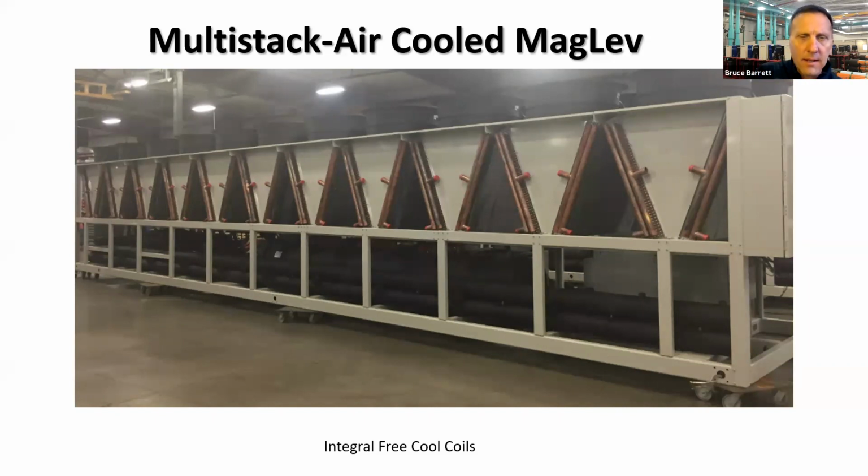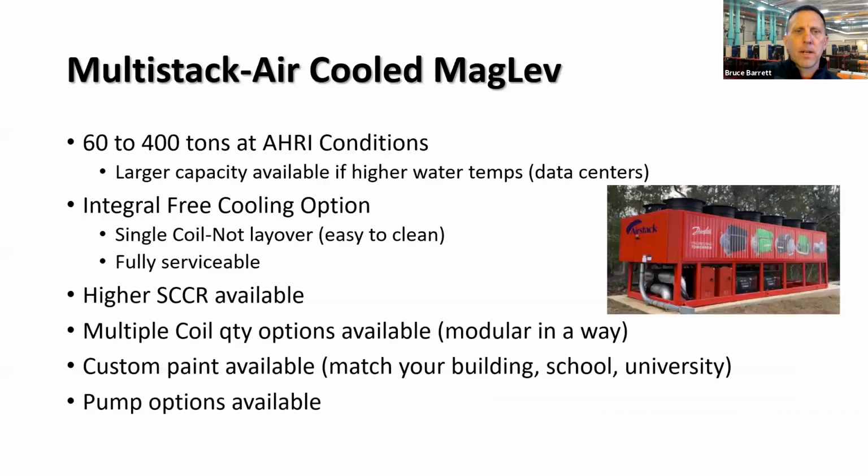This is an 11V. So it's close to 300-ish tons. We do go from 60 to 400 ton air cooleds. Again, larger capacity data centers, we might be able to go up to 550 ton, oftentimes because their leaving chilled water temp is around 58, 60, 63 degrees. So we can get a heck of a lot more capacity when the leaving chilled water temperature is higher.